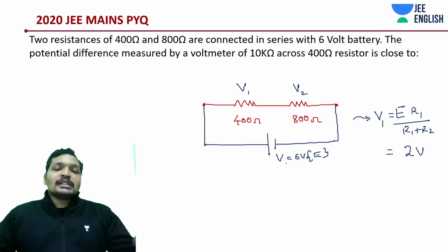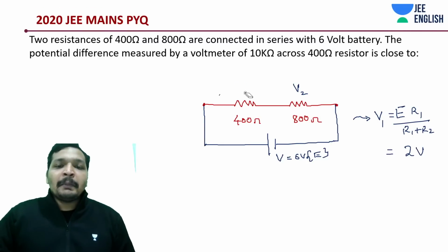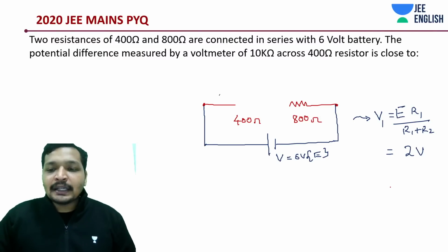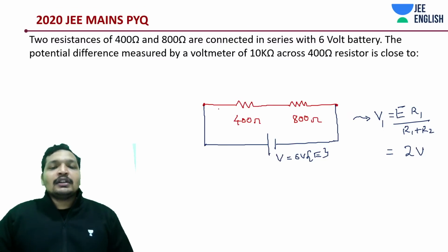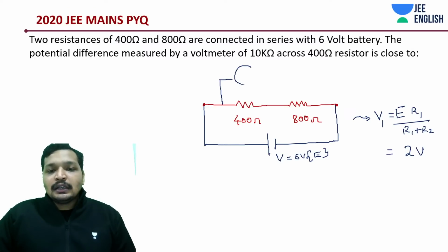Okay, now students, what is this thing? Voltmeter is always connected in parallel. Ammeter is connected in series. I am saying this hundreds of times so that you should not forget it during your exam. Very important. I've seen so many questions on electrical instrumentation, but this is a basic thing, students. You should be knowing it. There's nothing to remember.